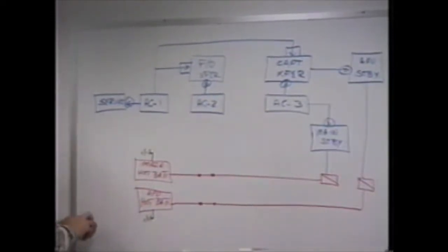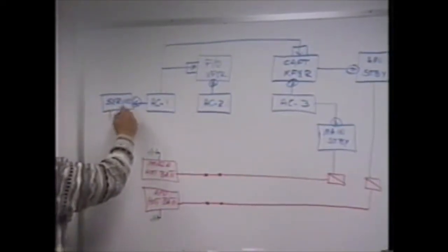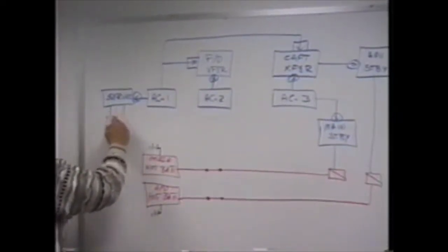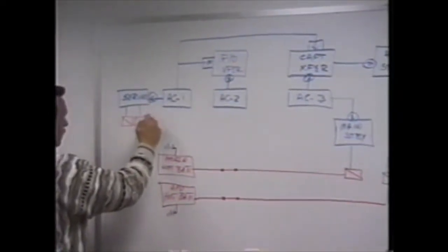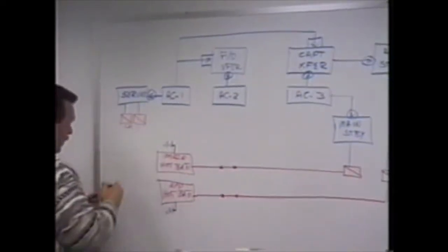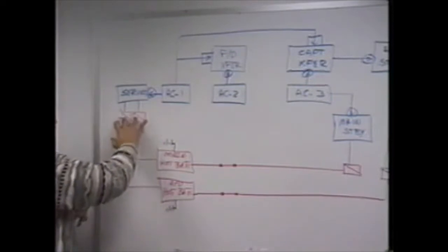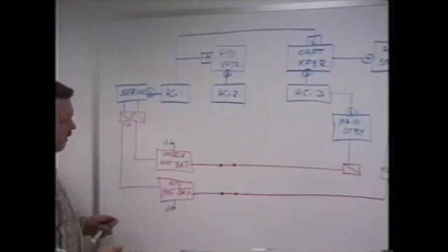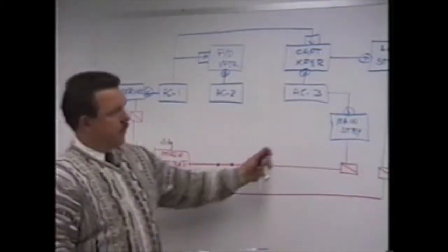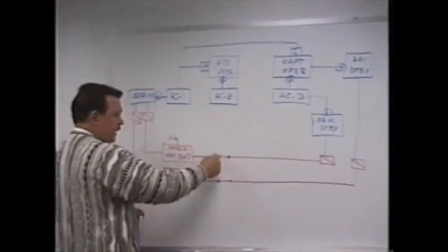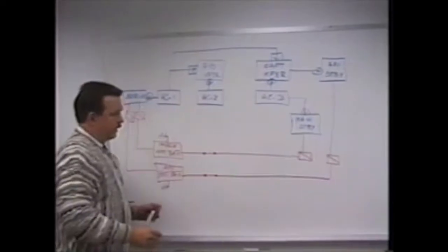The service bus gives us our 2 chargers. If the service bus is powered, your battery chargers are running, which are actually physically powering your hot battery buses and in turn powering your standby power system. In order for this power to occur, the battery switch must be closed.